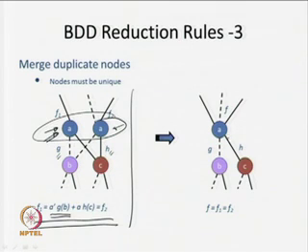When it is equal to A equal to 1 we are going to evaluate this sub function H, and when it is equal to 0 then we are going to evaluate this particular sub function G. So, like that we can merge these duplicate nodes and eventually we are going to get some sort of reduced or compact representation of our given Boolean function.